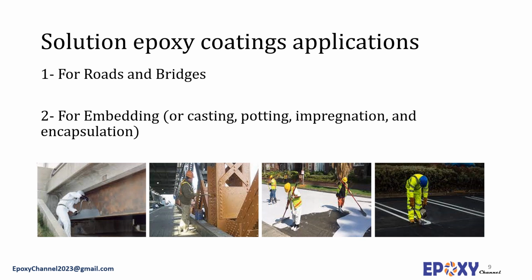Some other applications of epoxy resin coatings for roads and bridges include the repair of scaling concrete roads, the repair of slippery surfaces, protecting against fuel spillage, providing lightweight surfaces for bridge decks, incorporation of a waterproof membrane between concrete and an asphalt topping, as well as providing road marking and color surfaces.